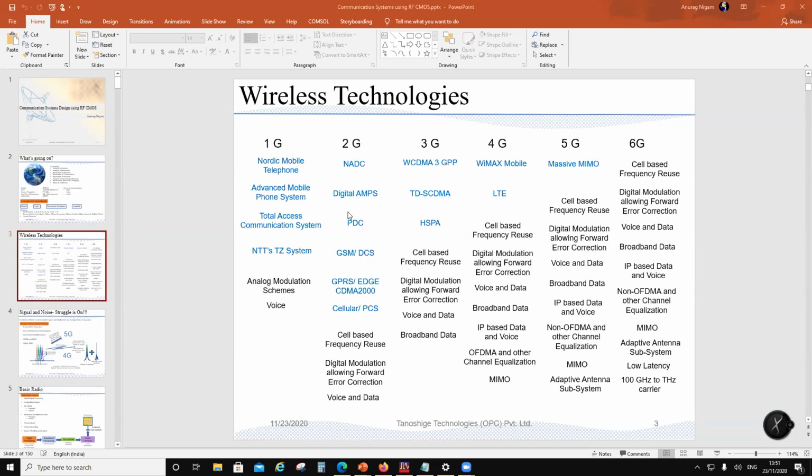In computer networks, it's mostly like time division multiple access. Okay, what they do is, let's say there is a Wi-Fi bandwidth of 2.4 to 2.5 gigahertz. In this, there are channels. So I can have certain channels for transmit, certain channels for receive. So still there is a frequency domain dependence. But again, the people are talking in different time slots. So basically, this is time division multiple access.